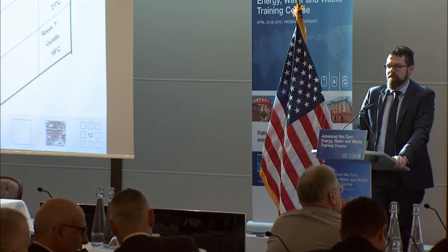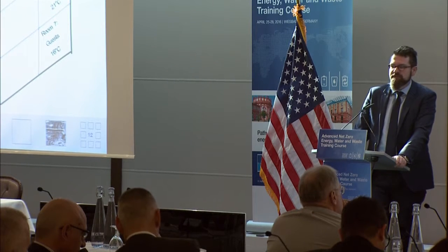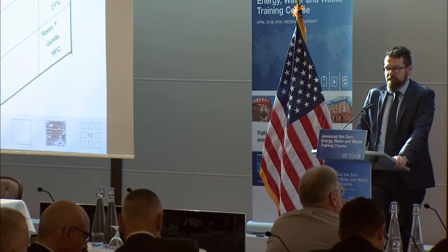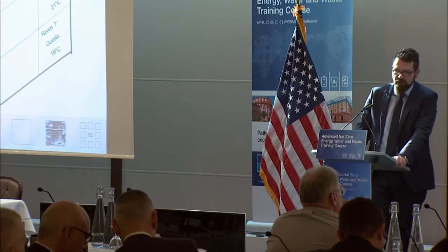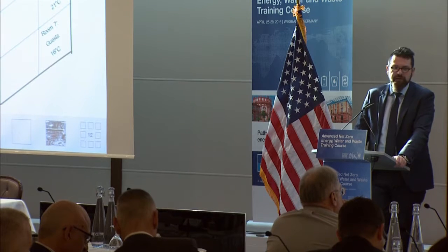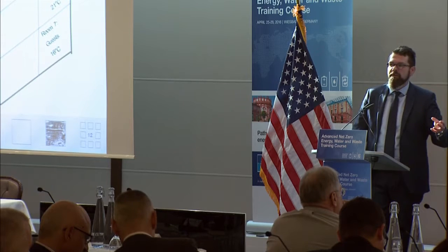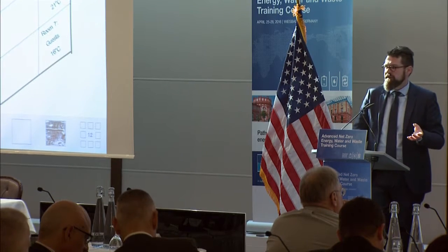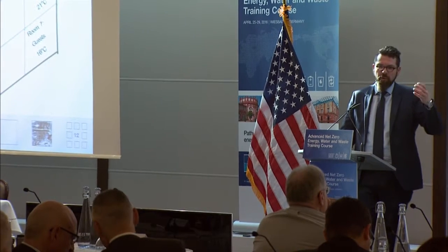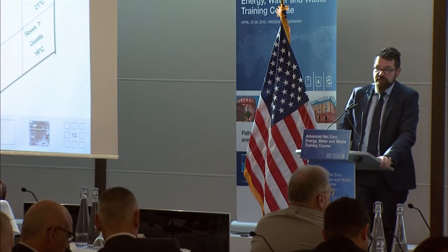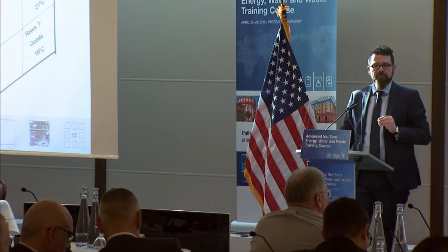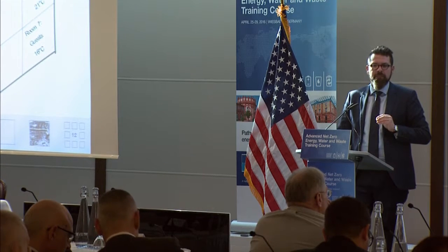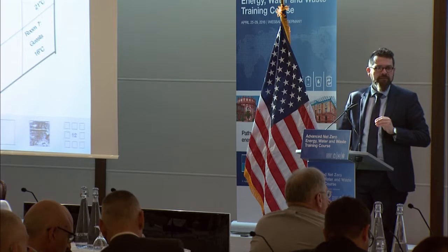If you have a look at one building, it's just the same. You have a number of rooms, and you have different temperature requirements in the rooms: a little bit higher in the bathroom, a little bit lower in sleeping rooms, in offices somewhere in between, living room a little bit higher, and a little bit lower in the kitchen, because you are cooking there, and you have the refrigerator, the dishwasher and such, so there you have more internal gains and the temperature can be a little bit lower. And now have a look at the time when you are using the room. You are not at the same time in a bathroom, in an office, in a sleeping room, and in your living room.